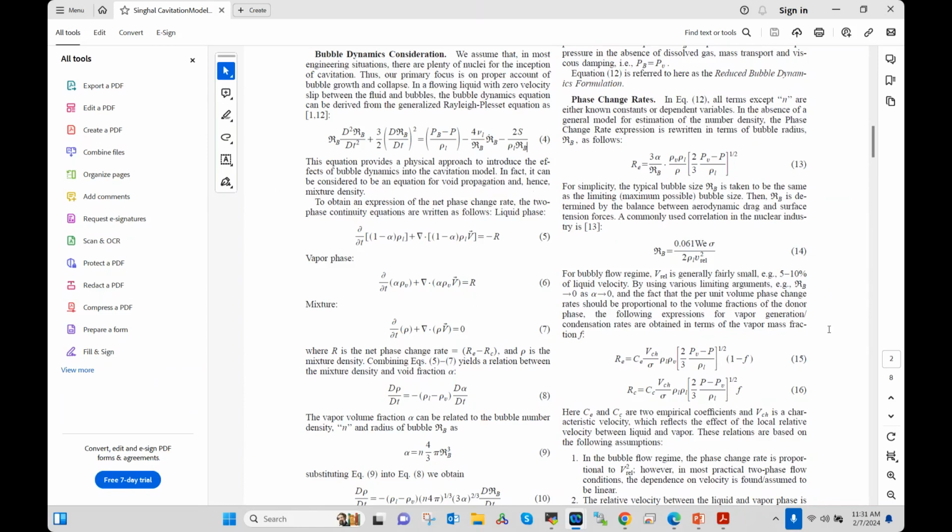From Sachin Kulkarni, for a coupled model, can we couple software like LS Dyna, which can give some complex motion to the mechanical boundaries? Yes, this can be done. All we need is basically how your surface is going to deform. We can take that spatial map, and then we can morph our geometry using our expressions to couple back and forth. So I think this is something that we have done in the past.